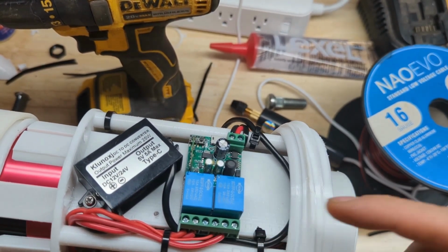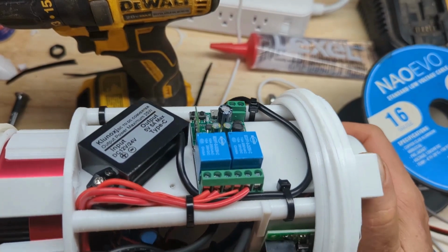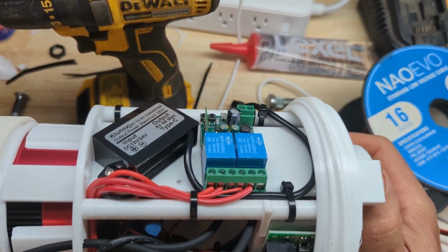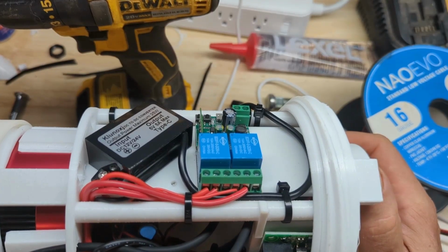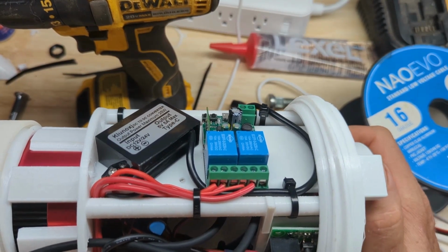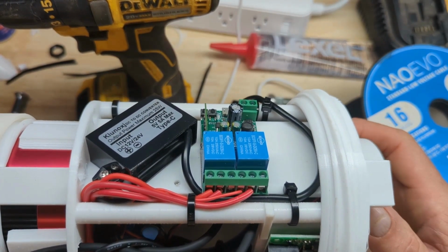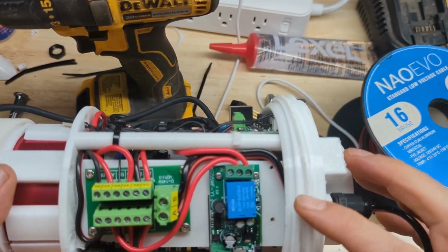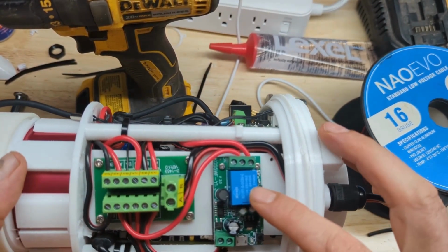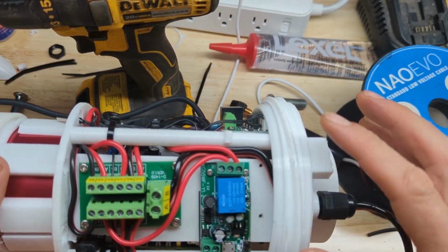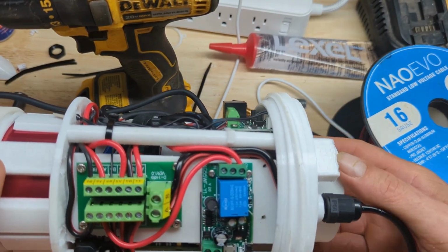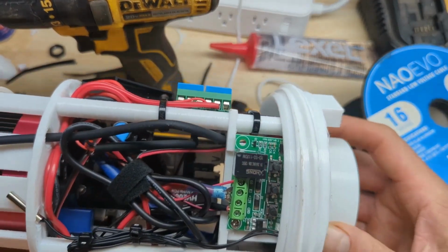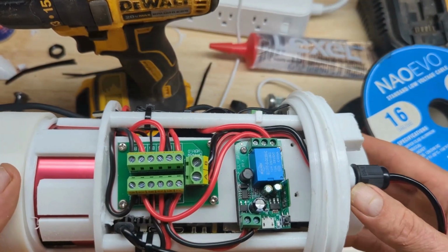But since these processes kicked on at different times of the day, like the dew heater, you don't need it on at 9 o'clock at night. Usually you're going to need it on at 2 o'clock in the morning when the temperatures start dropping, where it starts generating the dew in the dome or on the top of the dome. The solution was to move the dew heater off to its own Wi-Fi power switch. Once I did that, I haven't had any other issues with the camera going unresponsive. So that was kind of maddening to troubleshoot, but eventually got resolved and we're good to go.